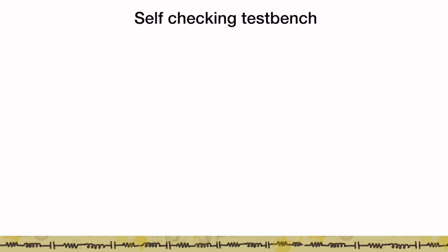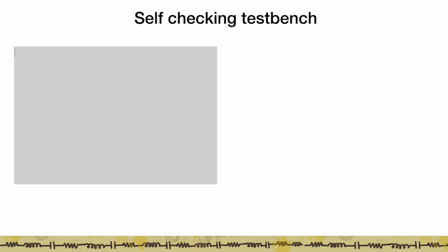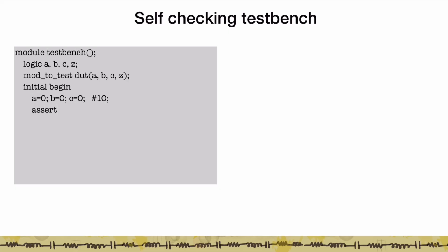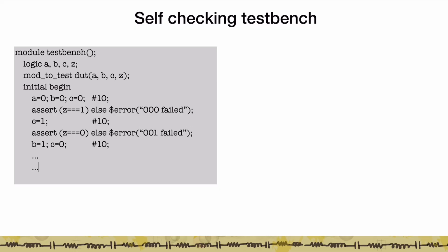So here's how I would convert the previous code into a self-checking code. Now what's the advantage of a self-checking code? The advantage simply is that it makes it easier for you as a designer to check your test benches. The reason is that whenever you do a design fresh, you have your mind space where you know clearly what the outputs are. But say you're looking at your design in 3-4 days, then it's possible that you don't remember the exact way the design functions.